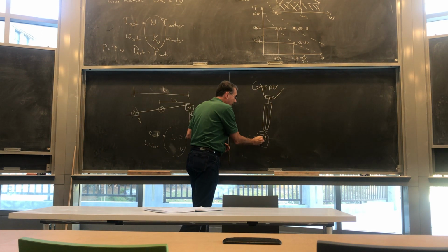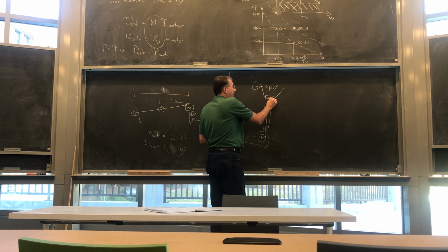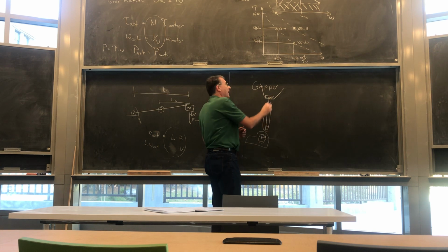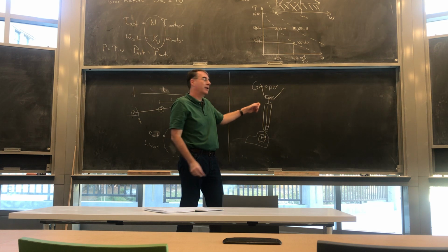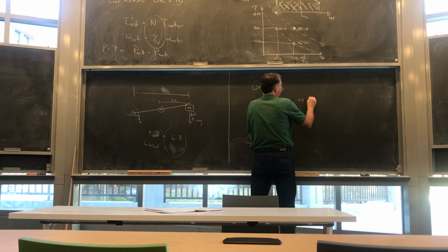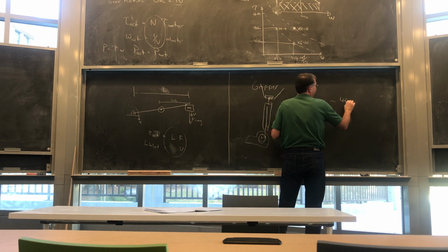There's a rotation times that radius to a length change. Then that goes through a rack and pinion to move the fingers. That finger has a radius that closes it, so there's a whole bunch of steps between. What it means is that the L effective is about 40 centimeters.